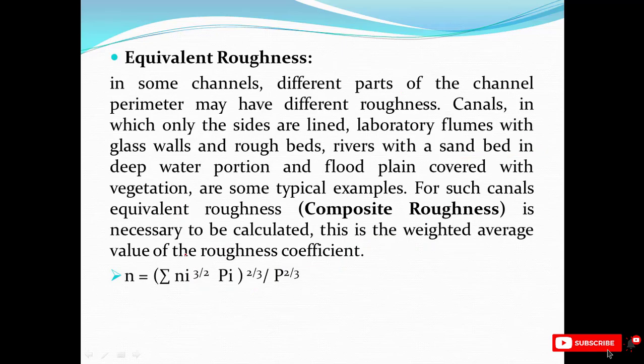Equivalent roughness coefficient. What is the equivalent roughness coefficient? In some channels or rivers, the material at the bed varies from the sides, so we cannot use only one value in the entire channel.